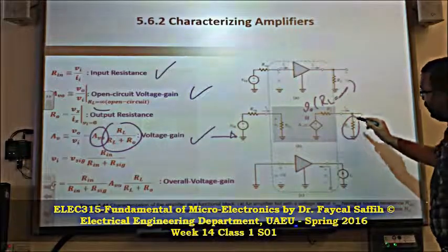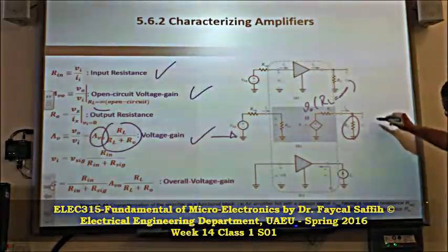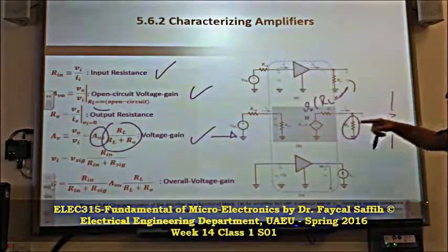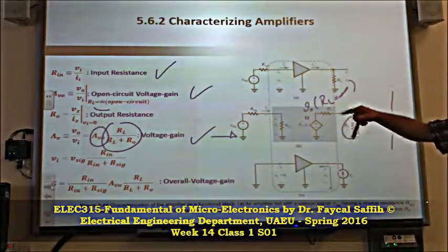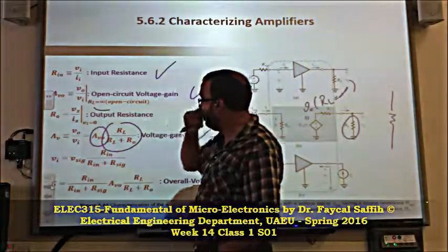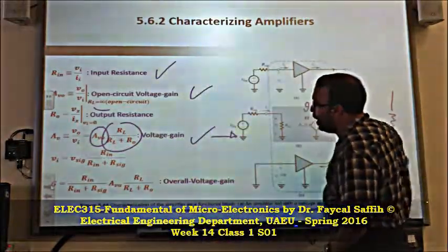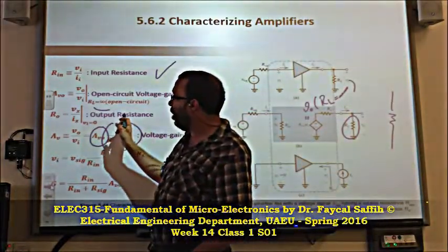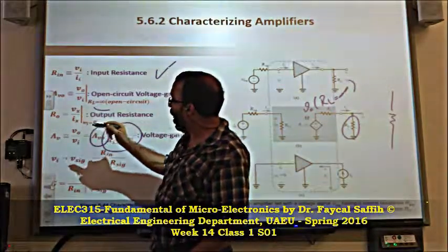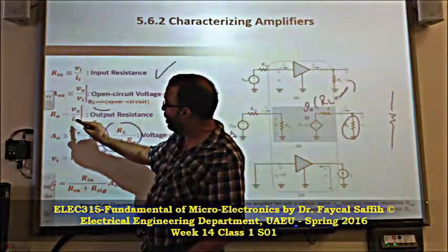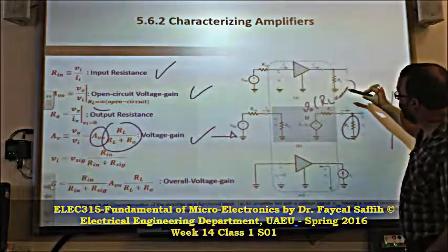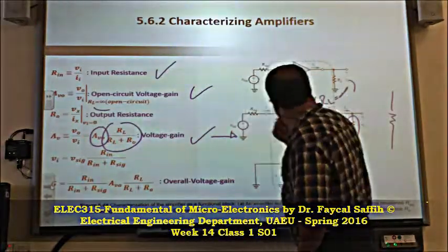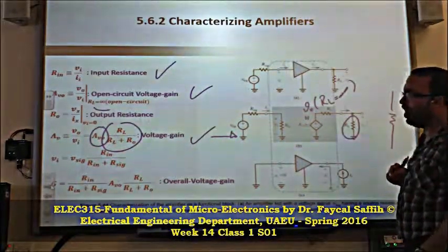Very good. So if I draw it again, I have here this resistance R out. Before this, we should have spoken about what R0 is. R0 is called the output resistance. Basically we send a current in at the output, then measure the output voltage and divide them.